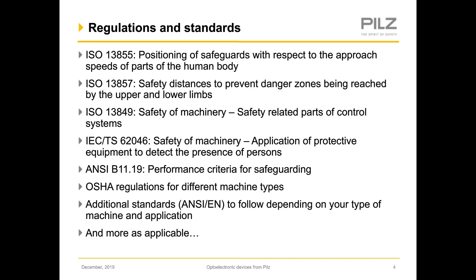Then you can also consult OSHA regulations for different machine types and additional ANSI standards or EN standards depending on your machine type and application. So for example, there are ANSI standards for robotics or for packaging machines and the like.